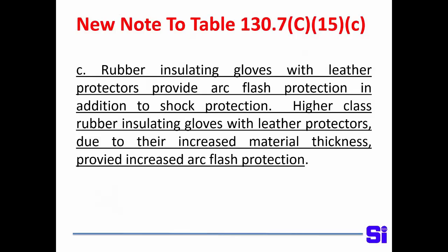And I don't know that I've seen anybody that's really had hand protection if they're wearing leather gloves and leather protectors. So you can wear what you like if you're racking out breakers or things like that. But if you're looking for shock protection, you have to wear rubber insulating gloves and leather protectors.